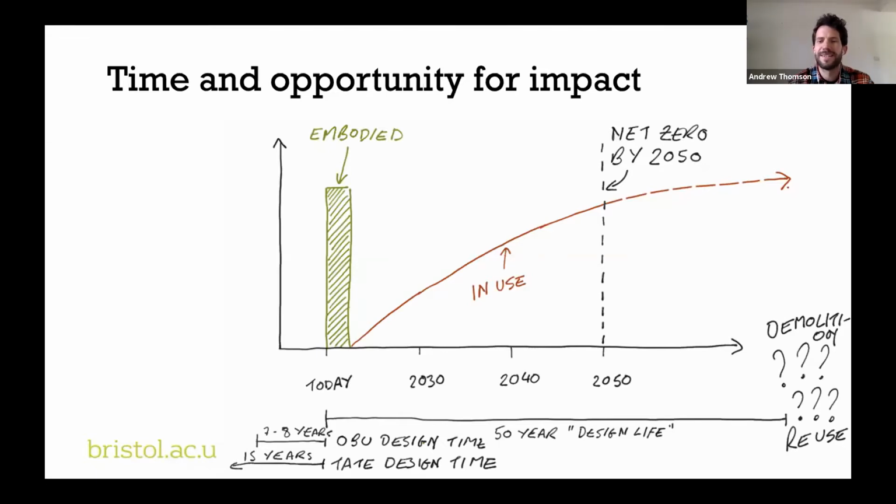Maybe like 20 seconds. I was just saying embodied carbon is kind of now, but in structural engineering terms, now means over the next 5 years. It happens over the next 5 years. Whereas the in-use carbon gets released during the use of the building. And actually that will carry on happening. And we tend to measure in-use carbon over the life span of a building, which is, well, we can debate that as well, but let's imagine it's 50 years because that is statistically helpful.